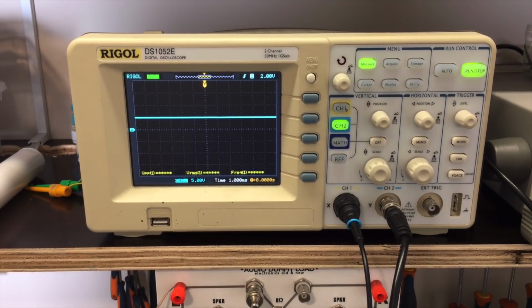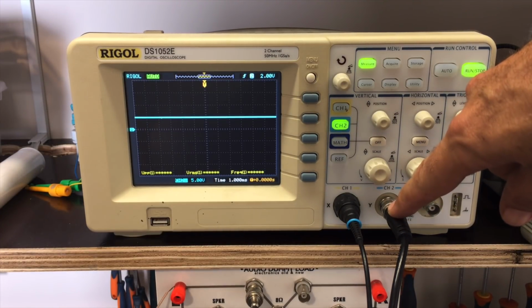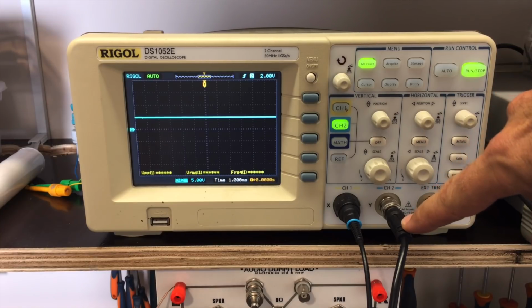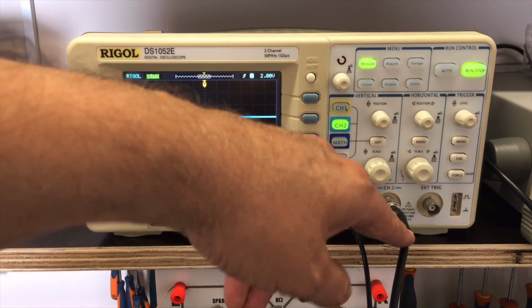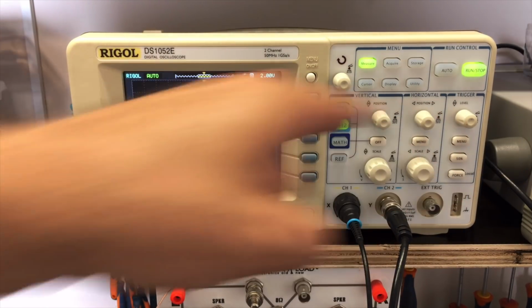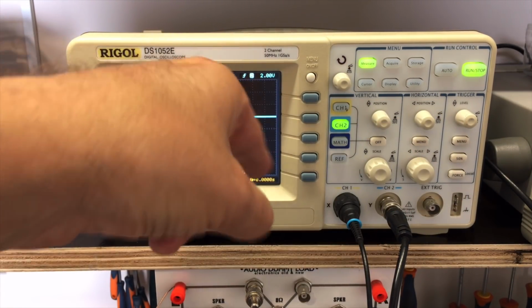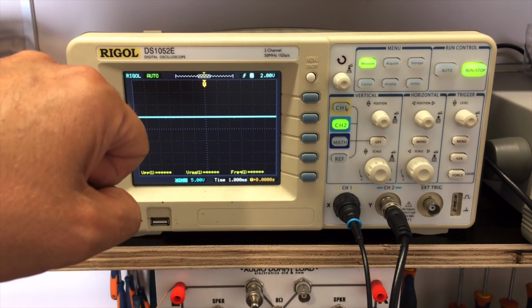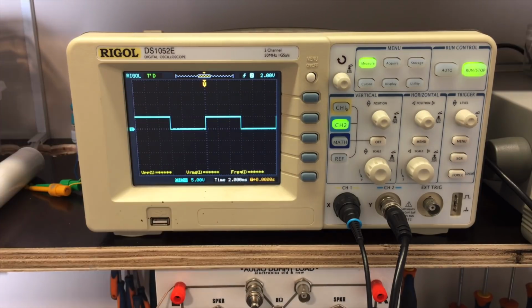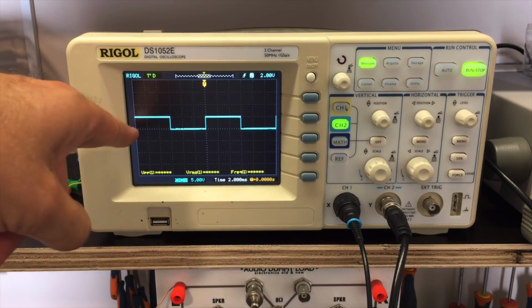Now this is where things get kind of interesting. If you recall, I had the sweep time to 12 milliseconds. What I've got coming into channel 2 of the scope is the trigger output signal from the signal generator. And what that means is that every time a sweep starts, this thing gives me the start of a square wave. And when it ends, the entire square wave is represented. If I turn the time base down, I've got it now at 2 milliseconds per division. What you're seeing here is effectively